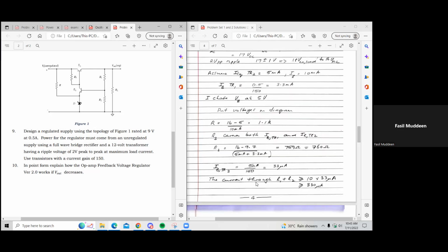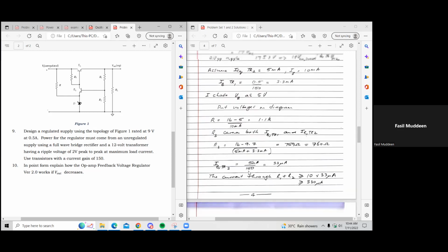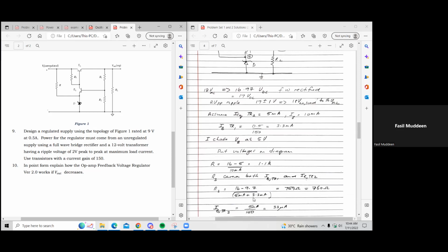Same thing with the transistors and so on. For typical small signal transistors, ICQ is typically about 5 to 20 milliamps. So I leave that up to choice, unless I'm more interested in how people go through the design rather than the actual answer. But if there was something specific that I wanted people to do, I will tell you to use ICQ or IZ equal to some value that I will give. If it's not given, you state that you're assuming that ICQ, for instance, is so and so, and IZ is so and so, and VZ too.